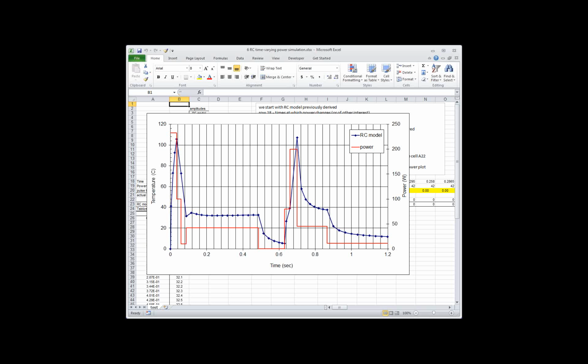And as for you can't do it, well, I don't know if anybody answered you can't do it. Obviously, you can do it. We just did it. And so I would say, kind of rule of thumb, anywhere between 1 and 2 rungs per decade is good. It just depends on how accurate you want to be. If you do 2 rungs per decade, you're well within 1%, more like 0.2 or 0.3%.